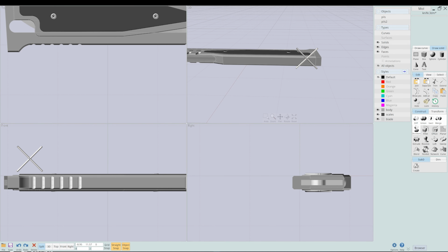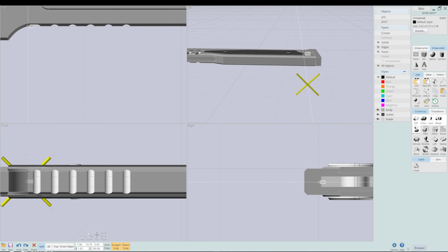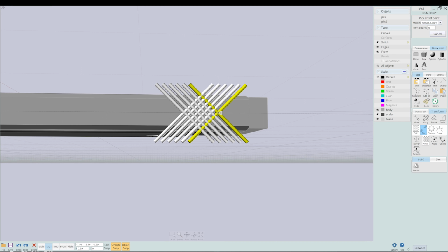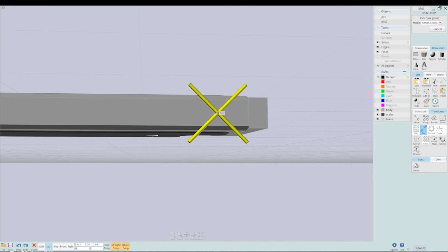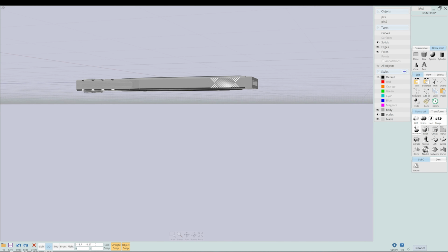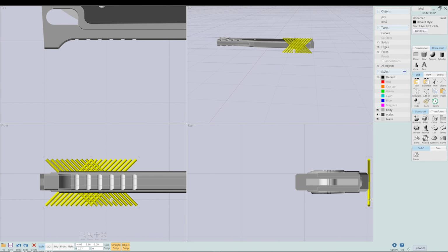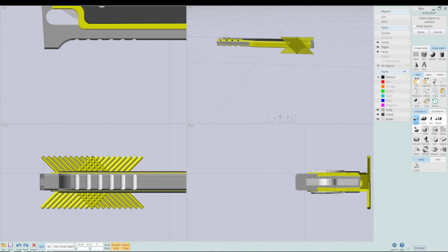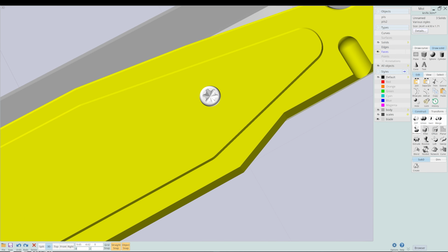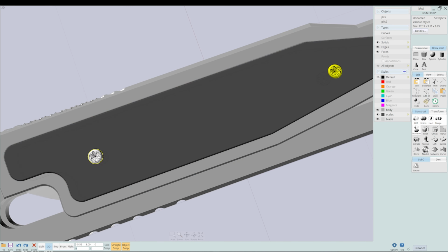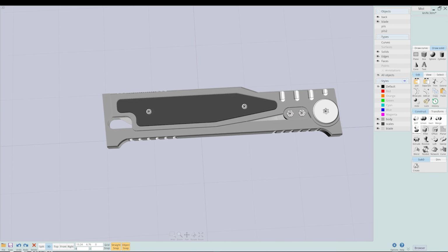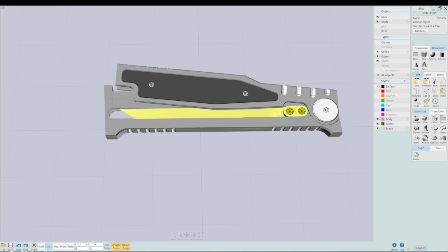Yeah, safe to say ZBrush is not the best tool for this task, and if you're gonna use it, you probably want to use the polygonal Z-modeler setup to do it, and just use the booleans to subtract out the blade face and stuff. I had such trouble because the blades are such shallow shapes, so using H polish and the type of stuff I usually do is not easy. But yeah, usually want to set up some of these color differences early on. It makes it a lot easier to read the model.